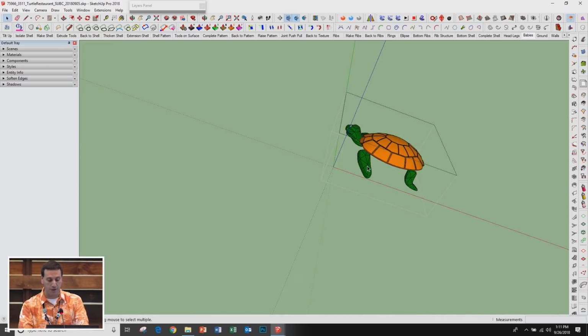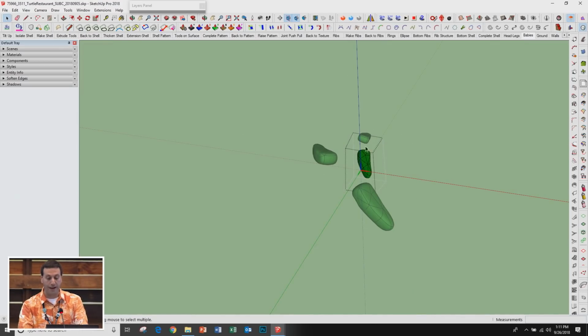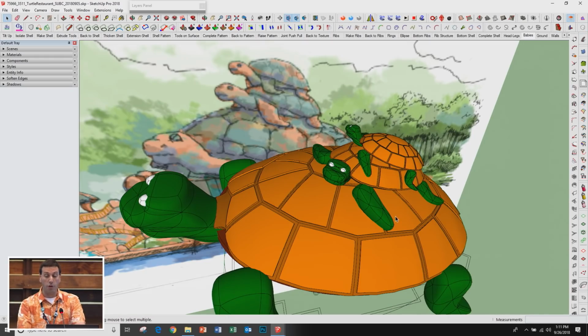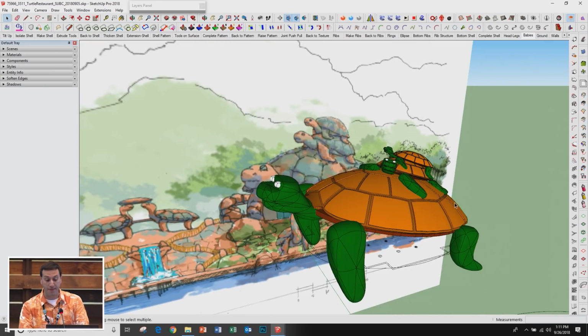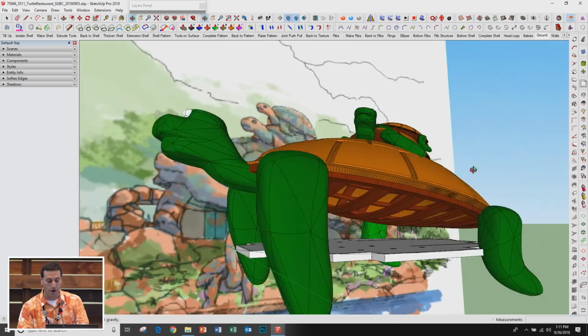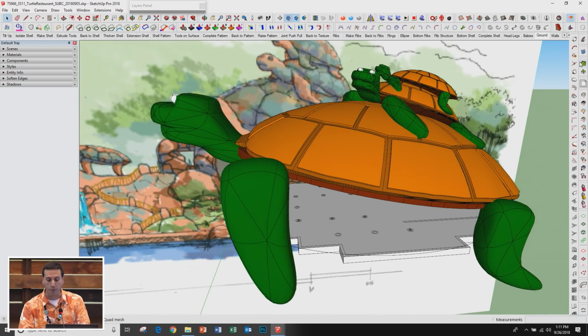And you know, these are all components, right? So I can go in there, and if I edit them, they'll all edit together. Use a lot of components for repetitive things. Otherwise, group all your geometry. This is a little preview of my session Thursday at 1:15. And then from there, I mean, that was it. That was the hard part, right? Because then I could put the ground in, because our architectural colleague had given me the ground plane.